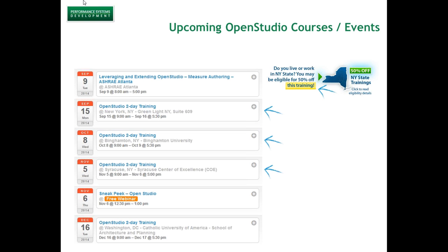And that's a very unique inheritance diagram in the sense that if you fully understand it, you can begin to leverage modeling with OpenStudio and make your models develop very, very rapidly. And you do that by applying a space type to a space, aggregating spaces in the thermal zones. That's one of the key principles in understanding OpenStudio: some of these object model properties don't exist in the world of EnergyPlus. They're really a piece of the OpenStudio model object itself. So that's a big piece in learning how to use OpenStudio, is how to understand and leverage this object model.